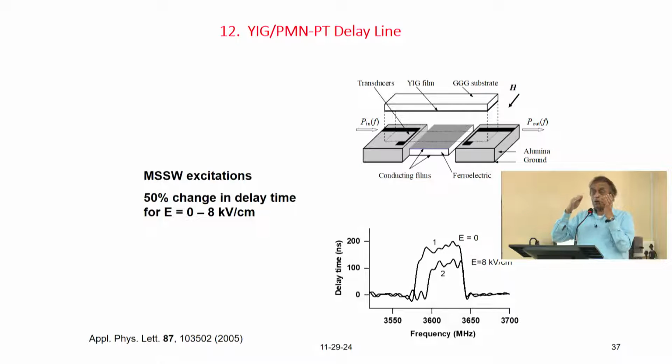So, that is where the delay lines come in. As the waves come in and propagate through the YIG, you can separate them in time domain using this delay line. It will convert the signal from the frequency domain into time domain, so that it will be received at certain time intervals, and that is what is shown here.